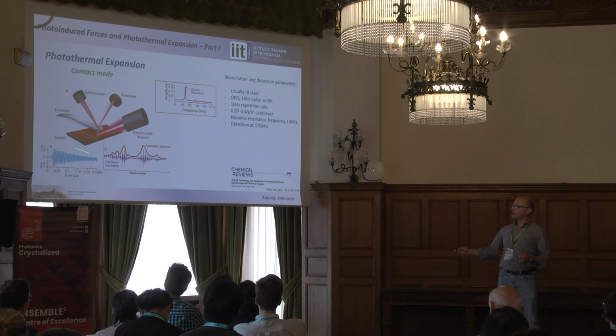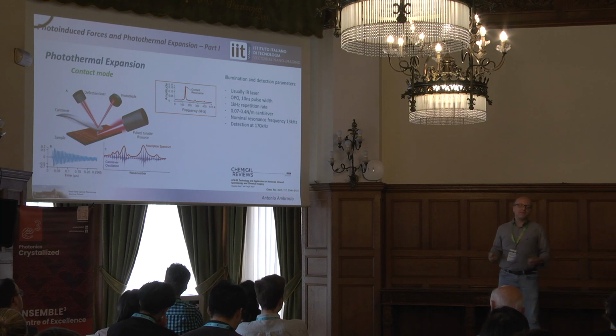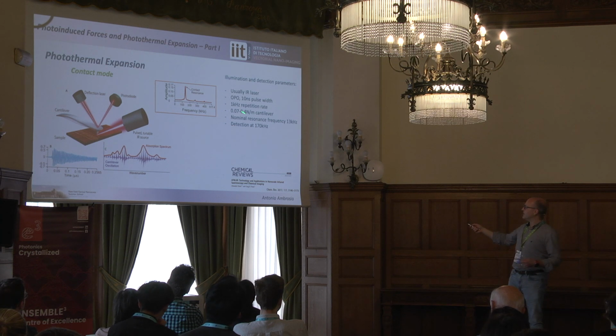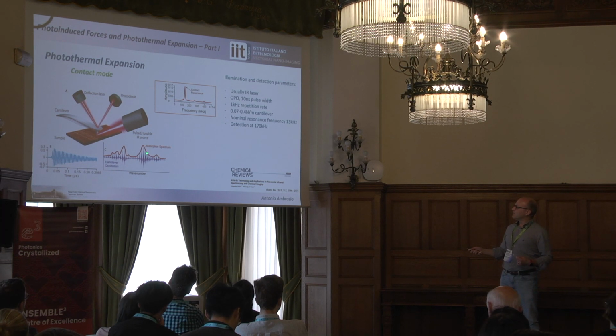But then you have this kind of amplitude as a function of time, and you can do a Fourier transform and look at the frequencies that are in there, and pick your frequency of choice. Typically, it's a mode that is far from the nominal mode. It's 170 kilohertz. But you usually select an electronic bandpass filter of 50 kilohertz to basically clean that from the background.